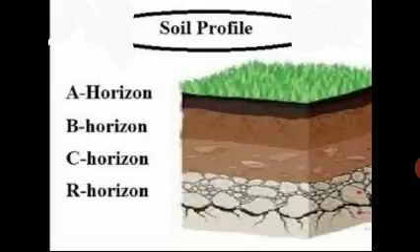The last physical property of soil is infiltration capacity. It is a very important factor. Infiltration capacity of a soil is the maximum rate at which soil is capable of absorbing water in a given condition. Infiltration capacity is expressed as centimeter per hour over an area. The larger the voids, the greater the infiltration capacity. Vegetated soils have more infiltration capacity. So these are the physical properties of soils.